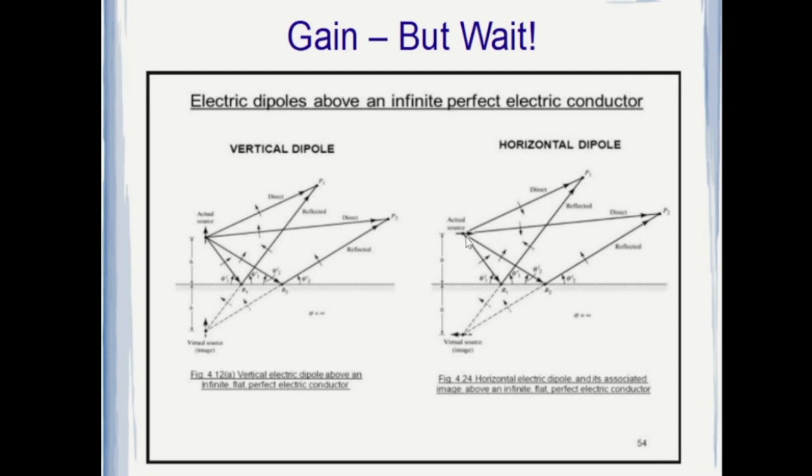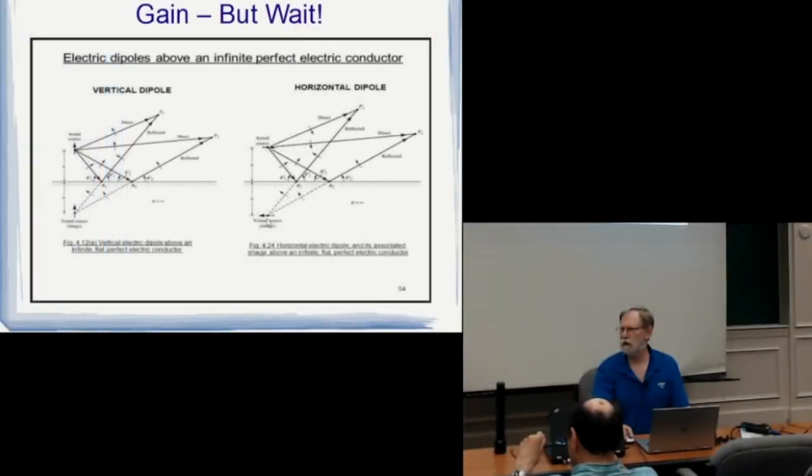So you get a signal from the antenna that strikes the ground, creates a new current, creates a new signal, and that signal is then summed at each point in the field. So essentially, you're kind of getting the contribution from two antennas. You're getting contribution from this one directly and from its reflection. Now, its reflection from these points appears to be down here underground, but its reflection is opposite in phase.